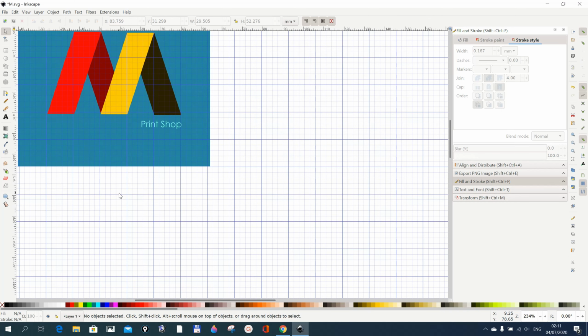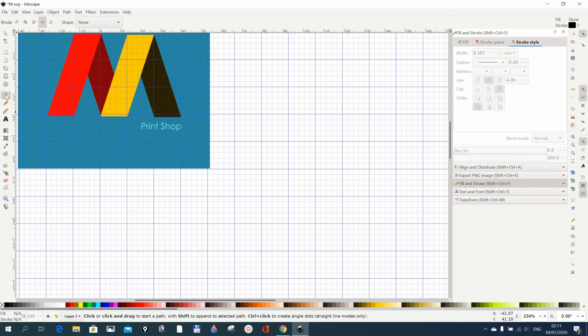Now we close this, and then we go for our Bezier tool, and choose the mode that we need, which is this one, sequence of straight line segments. So we are going to go from here to here, you click, and then use 3 boxes, you click, and then we go to the left, we click here, and then we come here to where we started. You see a red, and then you double click.